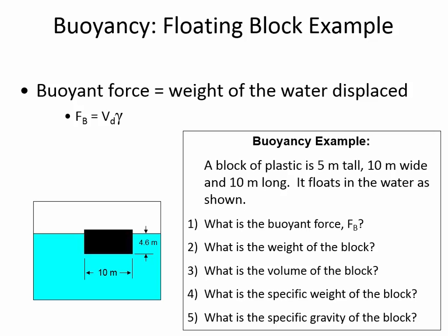The coal barges that you see going down the river are pretty low to the water. But the reason why it floats is that, even though the density of the coal is greater than water, here's the water, here's the barge. Probably they only fill it up this much, and then the other thing to keep in mind is that there are some voids there.